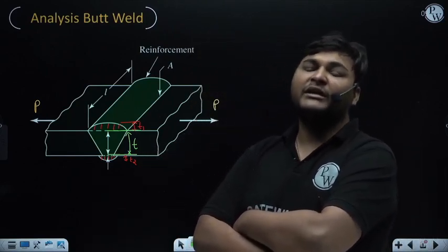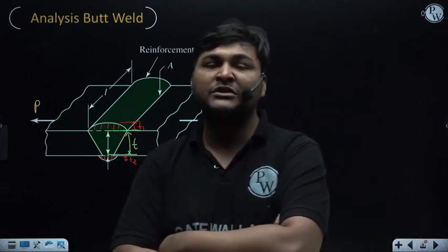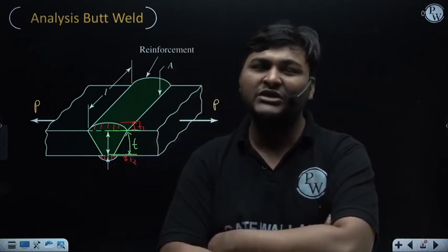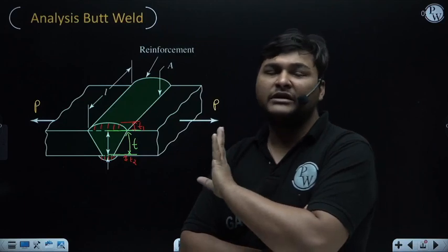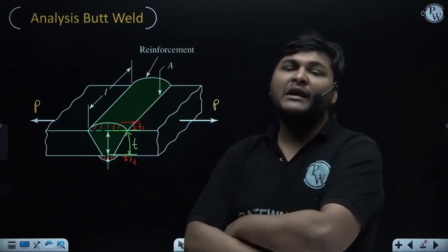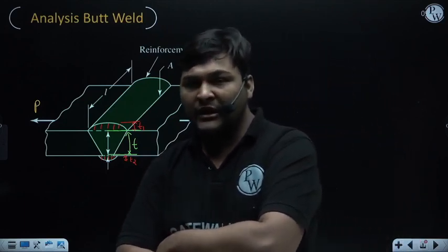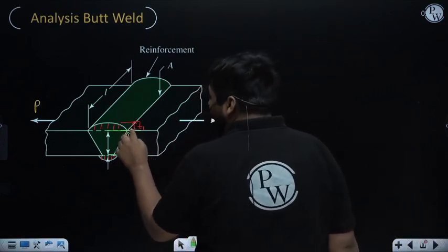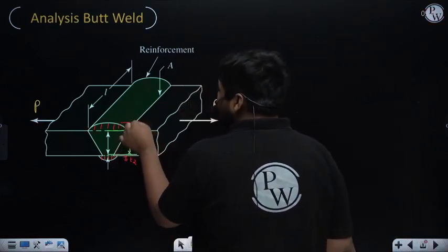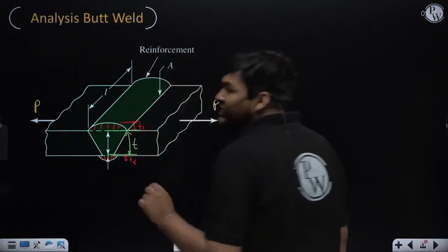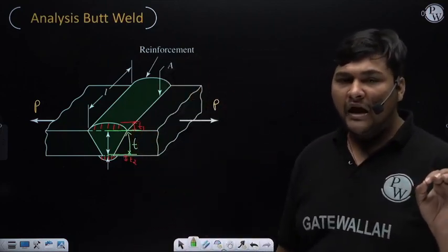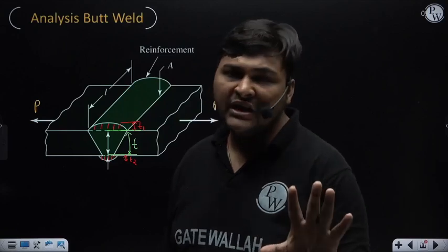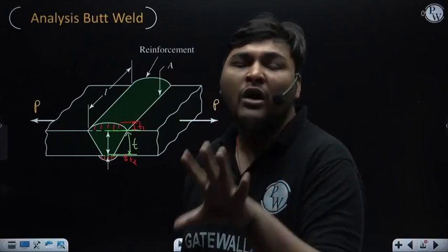But during analysis, whenever we calculate stress in the butt weld, whether the stress induced in the weld is normal stress or shear stress, that is a different thing. Whenever we calculate stress in the butt weld, the thickness of weld which is outside the plate, in this case T1 and T2, we will not consider.